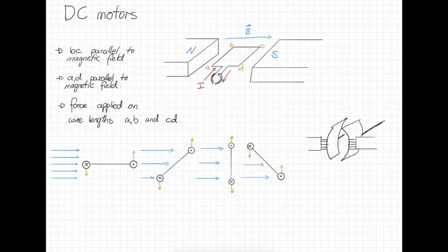At that equilibrium point where it's completely vertical, in a sense, we have no current traveling through, because that's where our brushes are not in contact. So it is its own momentum that actually keeps it traveling in the same direction. Because we have a force pulling it upwards all the way to that point, the force is still being applied until it reaches the vertical.